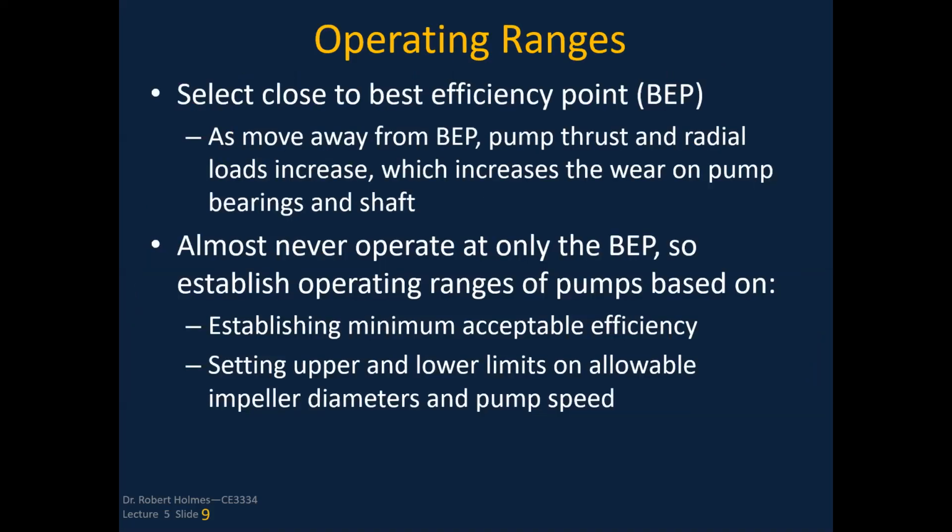Regarding operating ranges, our goal is to select a pump that's going to be operating at maximum efficiency. But as you move away from that, the pump will wear and might not operate as efficiently, so the efficiency will decrease. We want to try to stay in that maximum efficiency range if we can, but we almost never operate solely at the BEP. So you've got to establish in your design what your minimal acceptable efficiency is, and you can set the upper and lower limits on that.